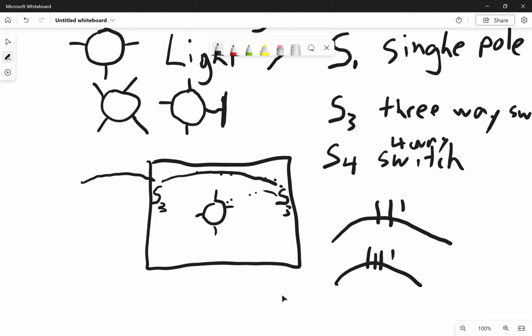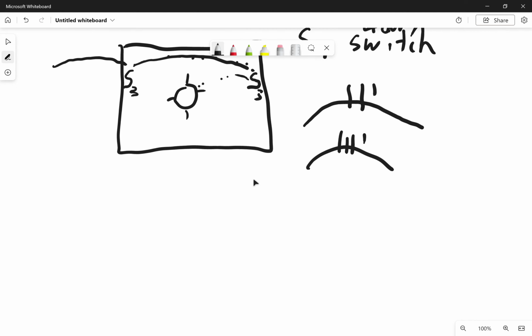And what that is showing you is how many current carrying wires are inside of that wire, right, inside of that cable. So if we take a look at a piece of cable, right, say this is a piece of Romex, and it is this one right here, right? It's a piece of 12-2, right? 12-2 means it has 2 current carrying conductors, right? Our 2 long slashes, those are our current carrying conductors, right?